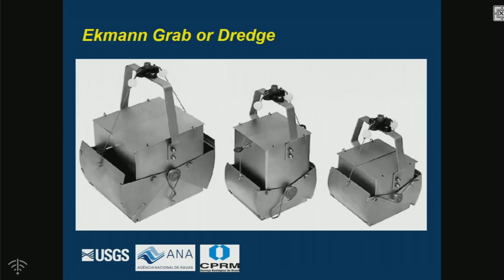There are a few different ways to go down in the lake to get a sample. Now think about a lake. You could take one of the other samplers, like the BM54, down, and it would collect a sample similar to this. But in a lake the velocities aren't there, so you can get by with some of these other samplers that would just drift down. In a river setting that wouldn't work, but in a lake they work fairly well.